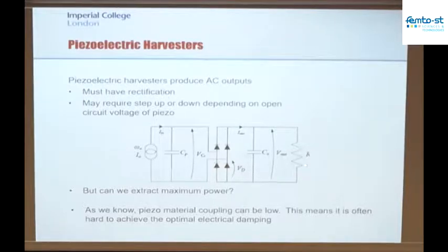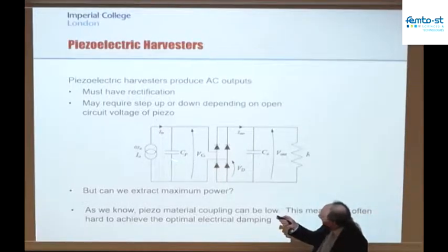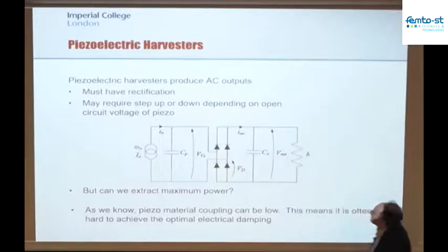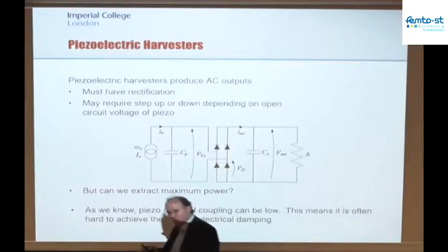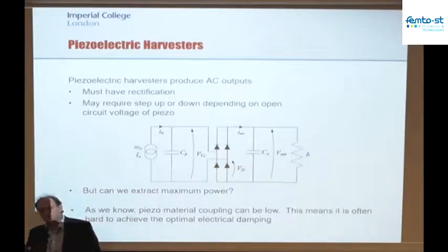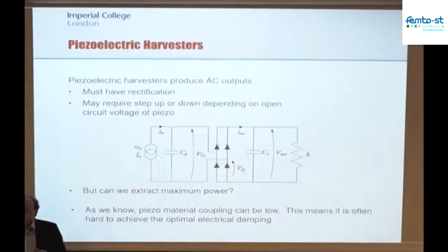The difficulty with this circuit is that there is no clear way here to be able to control the voltage on the piezo material. And remember, on an electrostatic based transducer, which could either be implemented with a piezo material or with a parallel plate capacitor, it's the voltage on the transducer that is going to influence the force that the mechanical system sees, and we've got to optimize that force to maximize the power. So we've got to be able to control the voltage on the piezo device to make sure we can operate it at its maximum power point as a system.